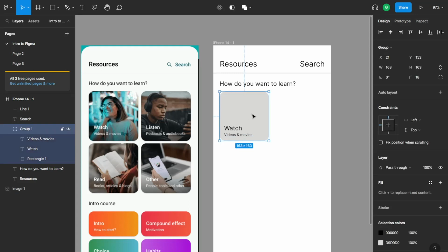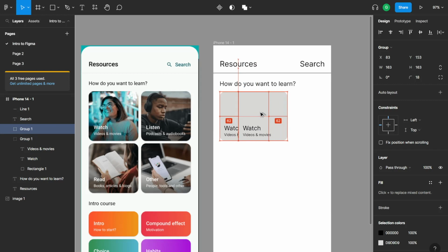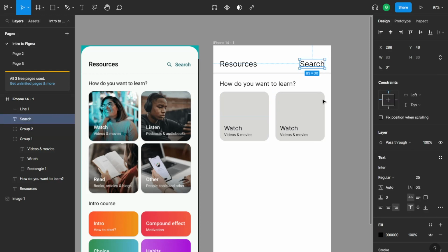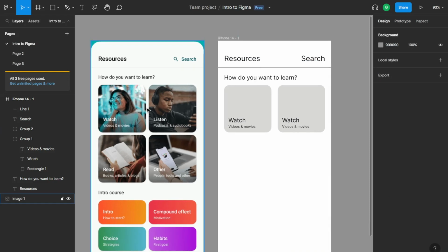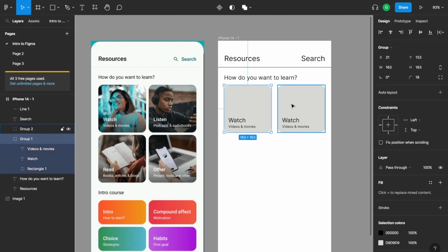Now we want to copy and create 4 of these squares. We've already learned how to do that very quickly. We select the item, we click and hold Alt and Shift on the keyboard, and we just move that item. And it actually snapped to this text over here. And cool, we can see from the example here that we probably want to make that a little bit smaller.